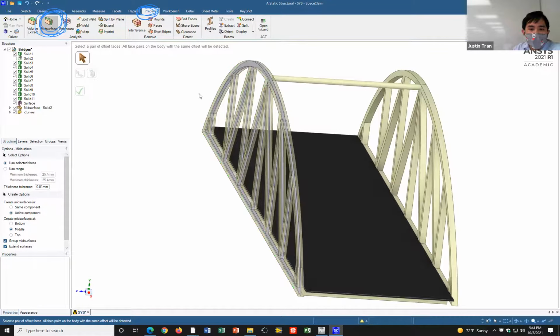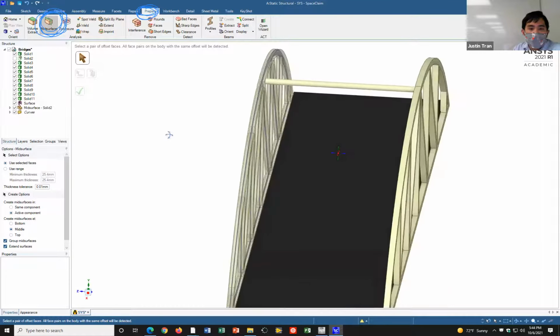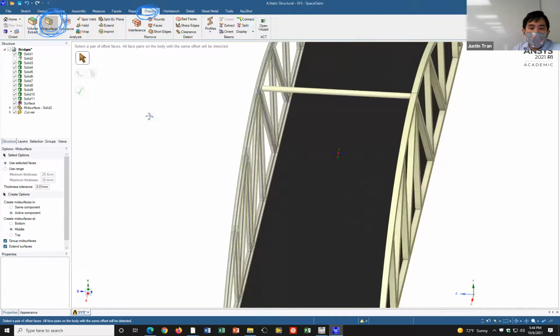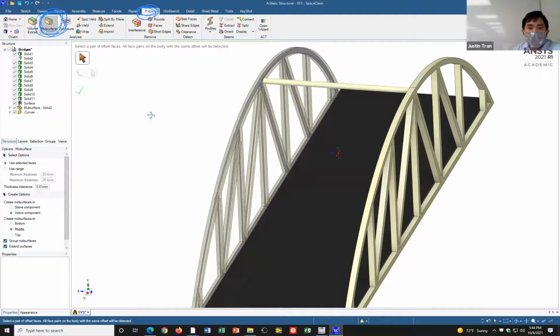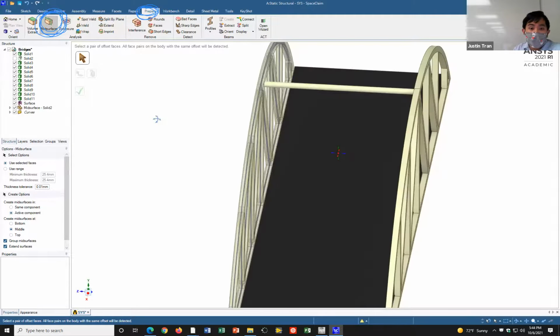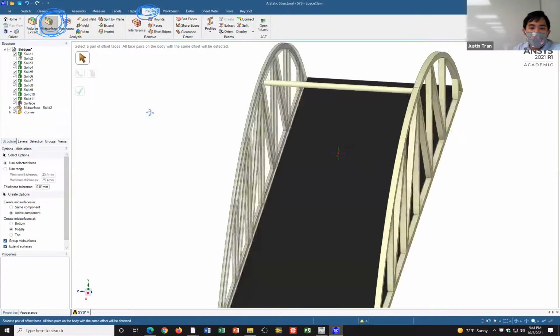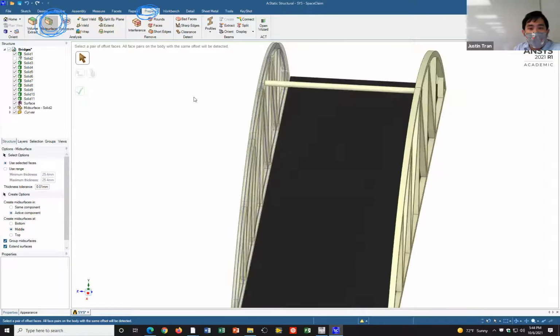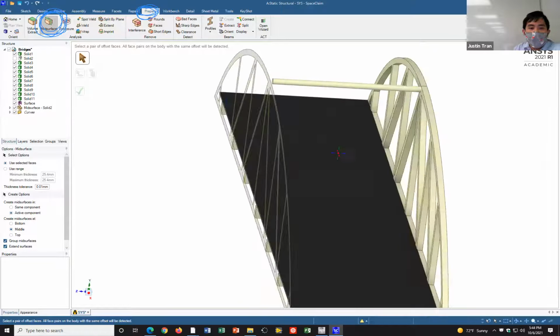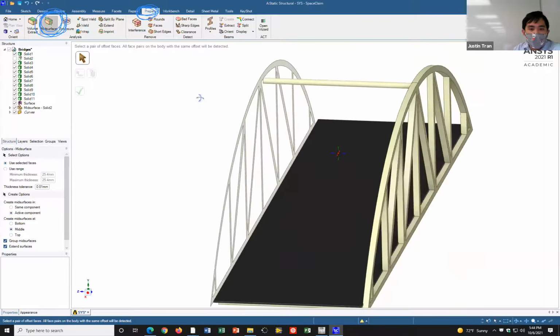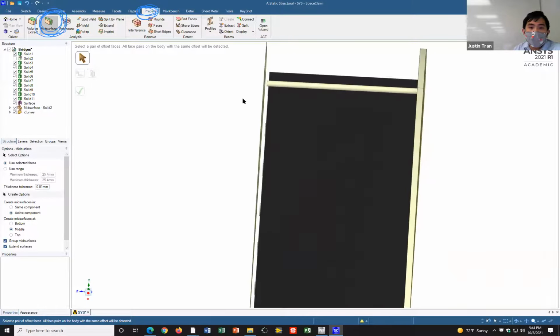And then after you do that, you can see that we've created this mid-surface, right? And so the original three-dimensional solid body that used to be there is now grayed out. And then in its place is this thin shell, okay? And if you actually left click anywhere within the window, you can see now that we have the shell of what it used to be. Okay.